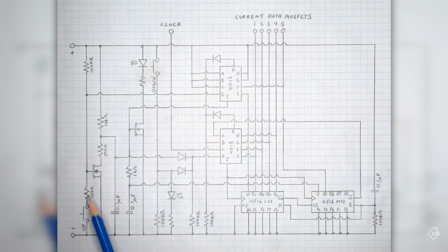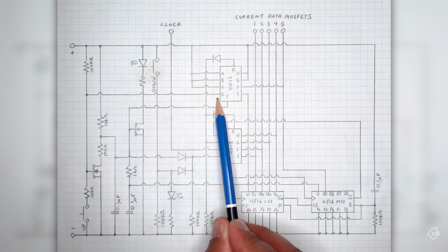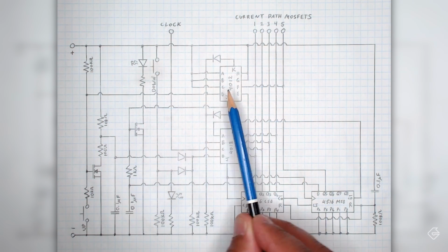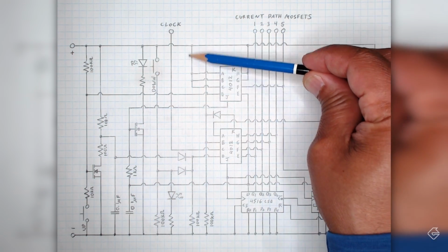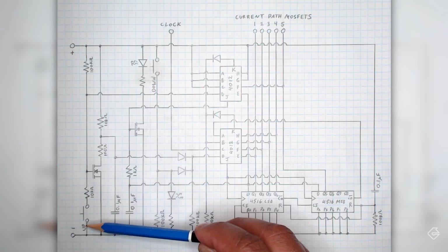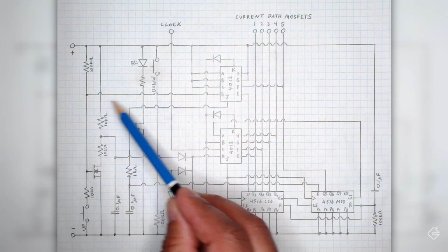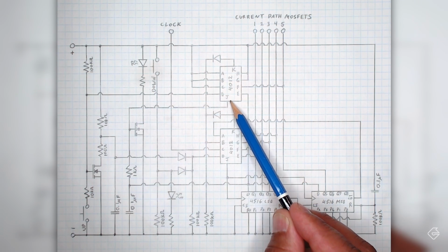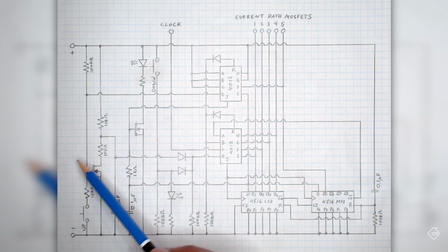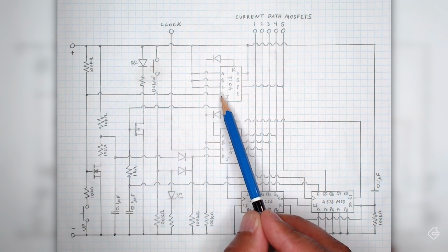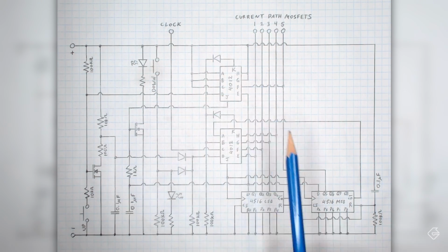You can actually see one of the leads coming up from this up switch, and it goes into the D input over here of the 4012. And the other three inputs are tied to high. What that means is whenever this up switch or that lead on D goes high, then the output, this J, goes low. And if the input on D is low, then the output J will go high. So this worked as a CMOS inverter.